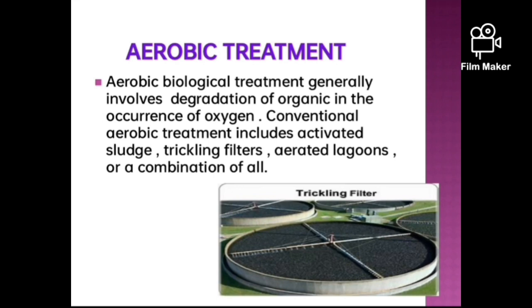Aerobic treatment. Aerobic biological treatment generally involves degradation of organics in the presence of oxygen, that is O2. Conventional aerobic treatment includes activated sludge, trickling filters.